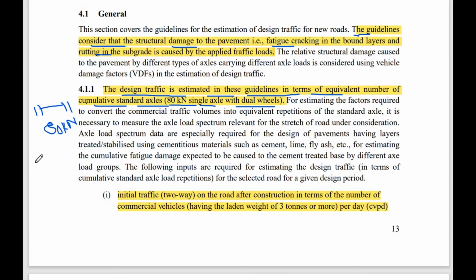As you might have observed, various vehicles, that means trucks or other commercial vehicles, have different types of axles, that means multi-axle, tandem axle, tridem axle. So to convert all of them into a single type so that it is easy to understand the impact of that particular vehicle on our pavement, we are considering the standard axle, that is of 80 kN, as our standard one.